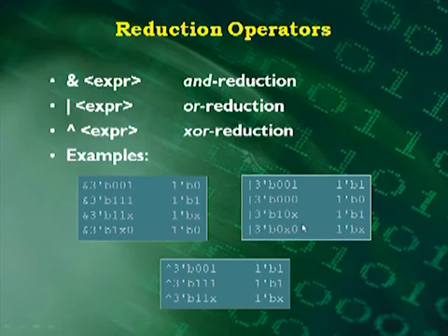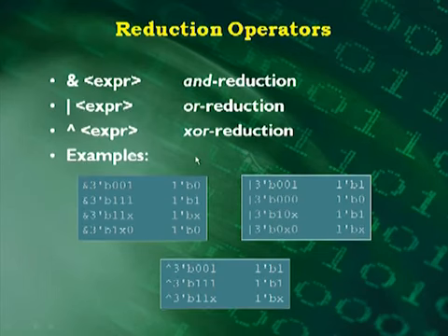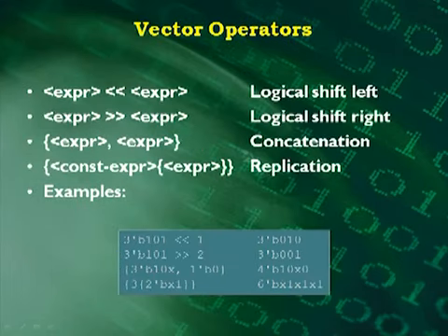What about X01? Okay, you're ORing those. So in that case, since you know you have a logic 1, it doesn't matter what you OR with a logic 1, you're still going to get a logic 1. And then here's another case for exclusive OR, and I'll let you look at that more in detail as you look at the recording of this lecture.